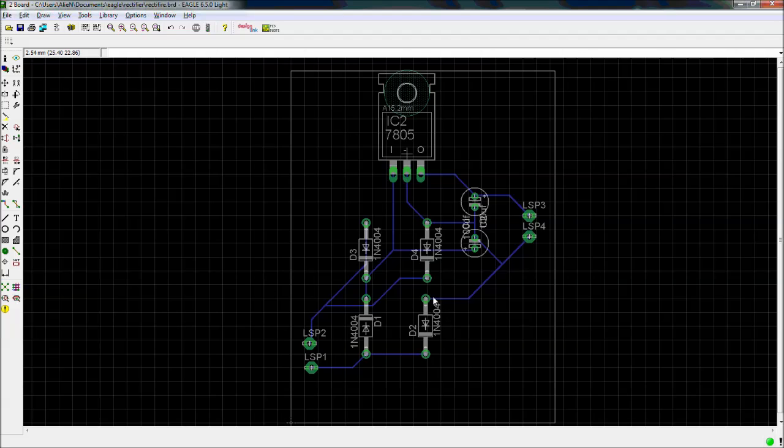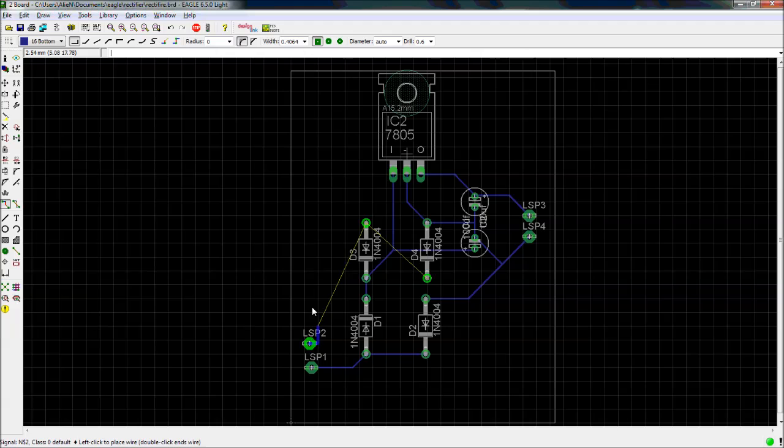Now if you want to connect it on your own, you can also use this route tool. For the time being, I'm unrouting any one wire. Check it out. Okay. Now you can connect it using this route tool. You can see this. It is moving in rectangle only because the rectangle wire bend is chosen. Now choose this other wire bend style. This will move the wires at a little angle. Right?